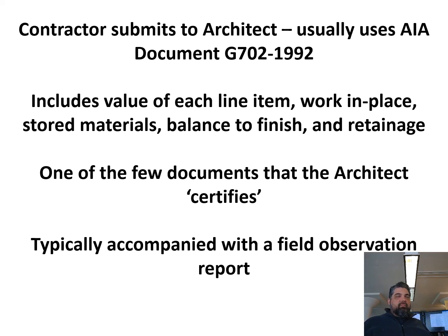The application for payment is one of the few documents that we as architects actually certify. And so when you sign it and date it, you are actually certifying that amount. It's one of the few times we actually do something like that, and so that's an important distinction there. And typically your pay apps are accompanied by a field report because, how else are you going to know what work is complete unless there is a site observation in order to see how much of that work is complete?